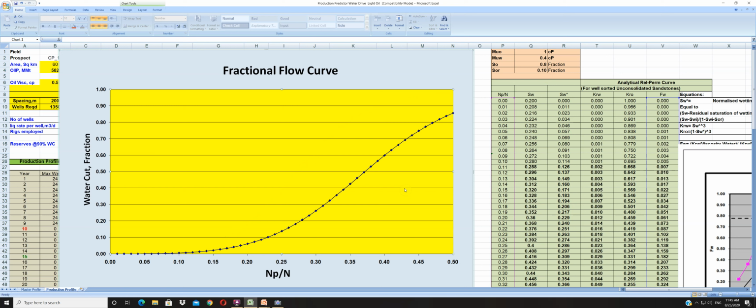If reservoir temperature is within allowable limits, salinity within allowable limits, and no divalent ion presence, you can well do it through alkali surfactant polymers. Surfactants are responsible for reducing the interfacial forces and dislodging the oil which is held by the capillary forces within the pores, and they make it somehow a bank and make it reach the producing end. So this is one way of providing a solution to what next.